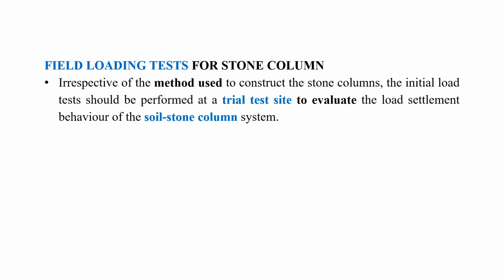Hello everyone. So today we shall talk about field loading test for stone column. It is also called the load test for stone column. Why do we go for the load test? To find out the ultimate bearing capacity or ultimate load on the stone column and settlement, or we can say the load carrying capacity of the stone column.